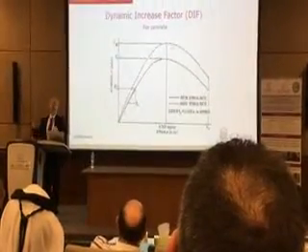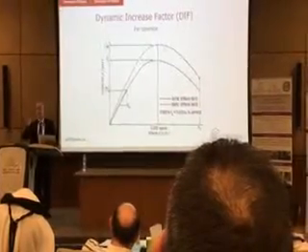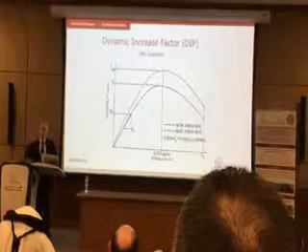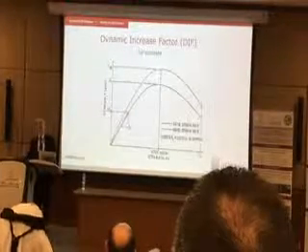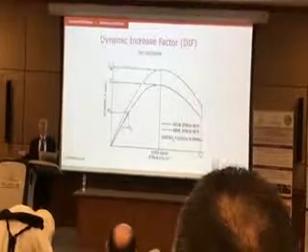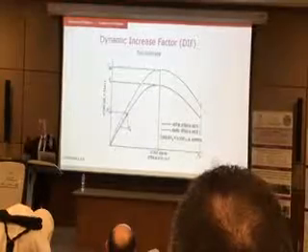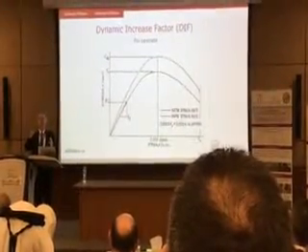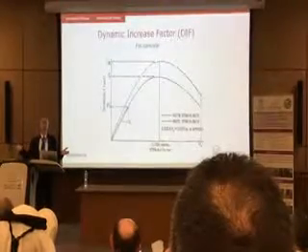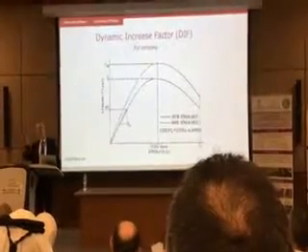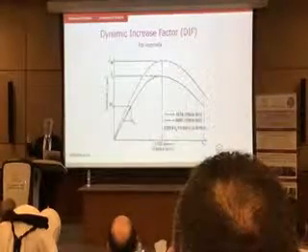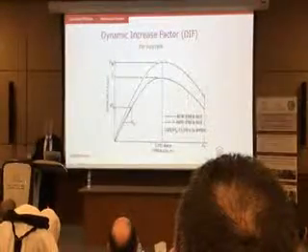But if you apply this load very rapidly at high strain rates, the strain that you induce is very high, as in the case of blast, material doesn't have a chance to fail. It's just like milliseconds, you hit, material is about to fail, but load is gone. So there is strain rate effect, and under higher strain rates, materials have higher capacities.